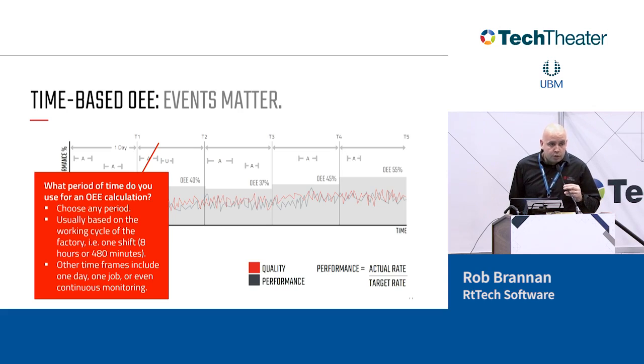So what that allows you to do is say, okay, I can have a shift summary. My OEE for the shift was, say, 70%. But what's made up of that 70% figure? Maybe you've done 3 product runs, 2 product runs are great, 1 wasn't so great. That allows you to analyse that individual product run, which is bringing your OEE score down, and allows you to understand how you can hopefully correct that in the future.